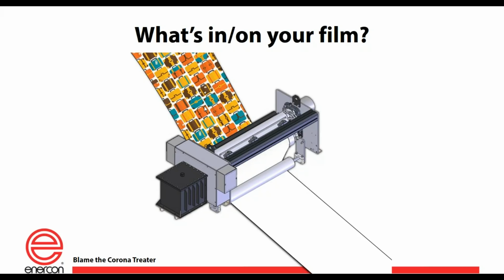So let's take two extreme examples here. We'll have just a virgin polyethylene film in one example, and then we'll have a polyethylene film that has a high slip content and a bunch of anti-block. Now, if you're not aware of these details, and all you were paying attention to is that the film is polyethylene, and you put the job up on the press and you're running these two jobs, not paying attention to the differences between those two films, it's very understandable why in one case you'd be successful at a given corona treater setting, while in the next case with the same setting, you would totally not be successful.